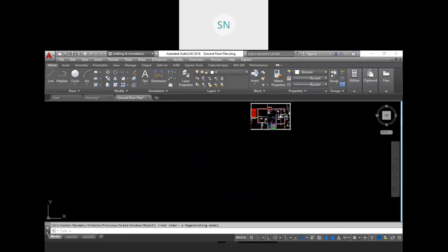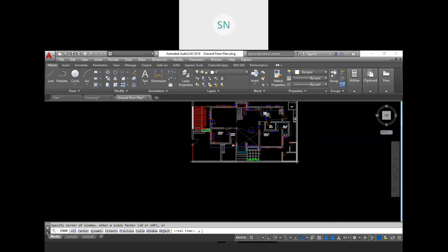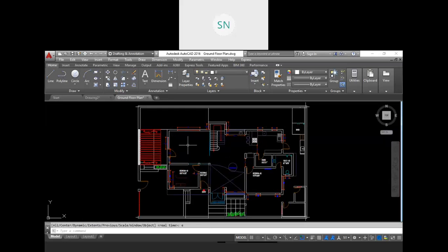How? For example, you want to create a center line plan, right? Just turn off the furniture, the text layer, and all the other layers you have, and turn on your center line layer. So it will give you the center lines, right? Then turn off that center line plan and turn on your furniture. It will give you a furniture layout. Turn off that furniture also and turn on your electrical layout, your wirings, right? So it will give you an electrical drawing. In this way, with only a single drawing, you are able to create multiple things. That's why we have to work with layers.